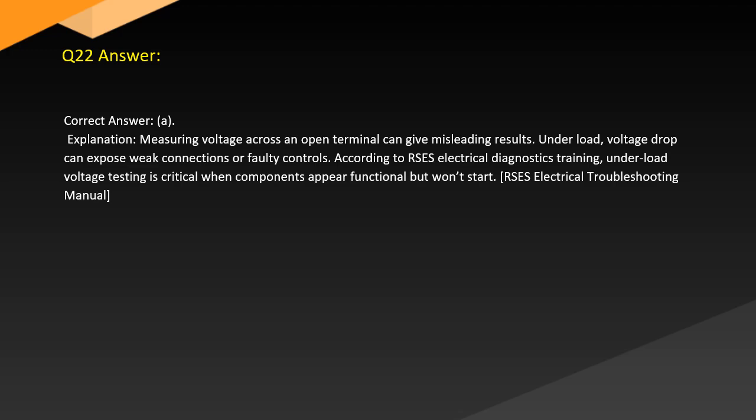Answer. Correct answer A. Explanation. Measuring voltage across an open terminal can give misleading results. Under load, voltage drop can expose weak connections or faulty controls. According to RSES electrical diagnostics training, under-load voltage testing is critical when components appear functional but won't start. RSES electrical troubleshooting manual.